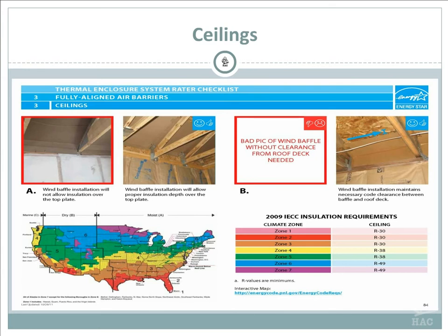Again, we were talking about the baffles in the attic. Right now, you're going to see where this baffle on the left is blocking all the insulation from getting back in there, and the wind is going to come in, but it's going to give you a void of insulation right in here because you're not able to cover it.